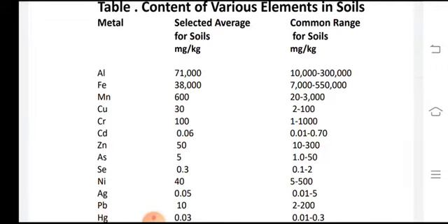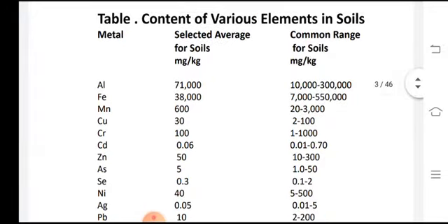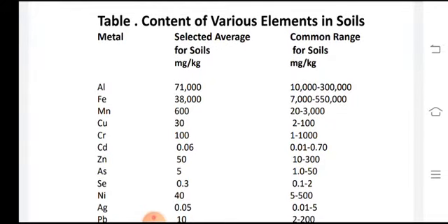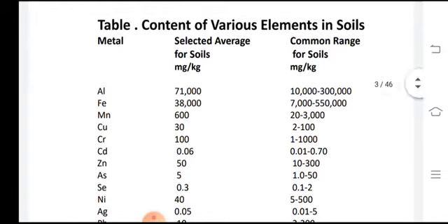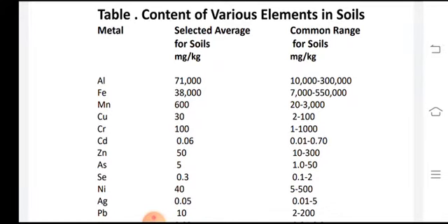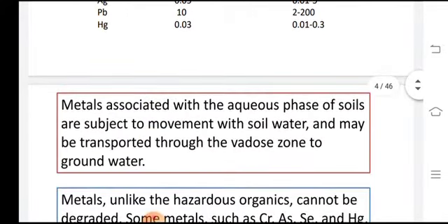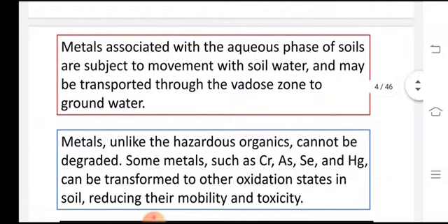So that will be measured as concentration in milligrams per liter, but this one is the attached or adsorbed portion of that concentration of solute which has entered into the soil, and this is giving us the amount in solid measurements, which is milligram. So milligram per kg of the soil sample, this is how we will be measuring it.